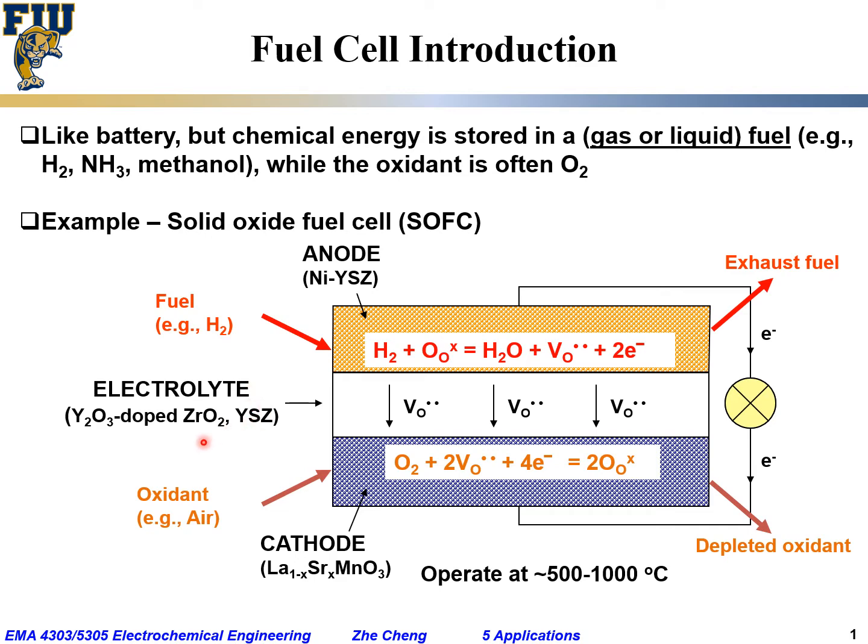It's actually an oxide ceramic called YSZ, or yttrium oxide stabilized zirconium dioxide, or yttrium stabilized zirconia. That is the center dense solid membrane. That is our electrolyte that conducts ions.